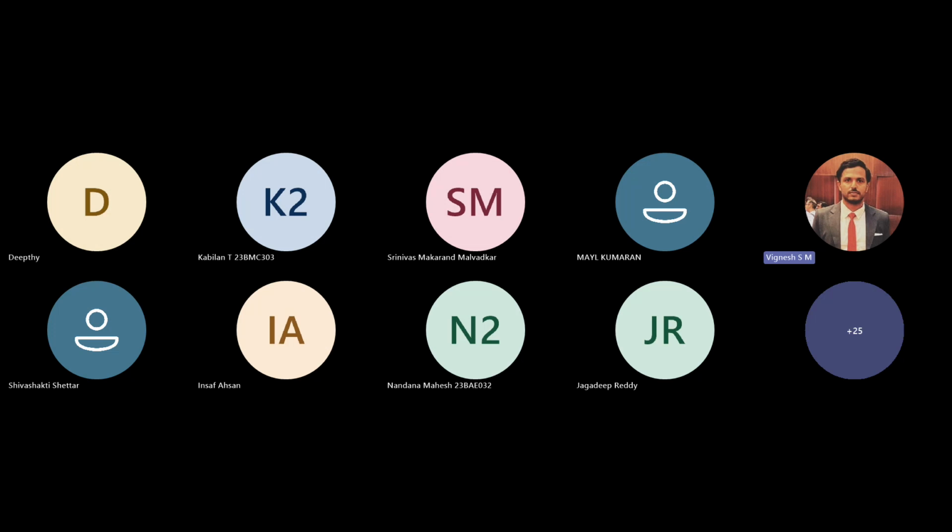Maybe for 2 million, I got 20 Newton. For 2.5, I got 25 Newton. For 3, I got 25.6. So I can stop with 3, right? The difference is extremely negligible, even if I go 0.5 million extra. That's how you have to fine tune your mesh. That's how we need to do a trade-off.